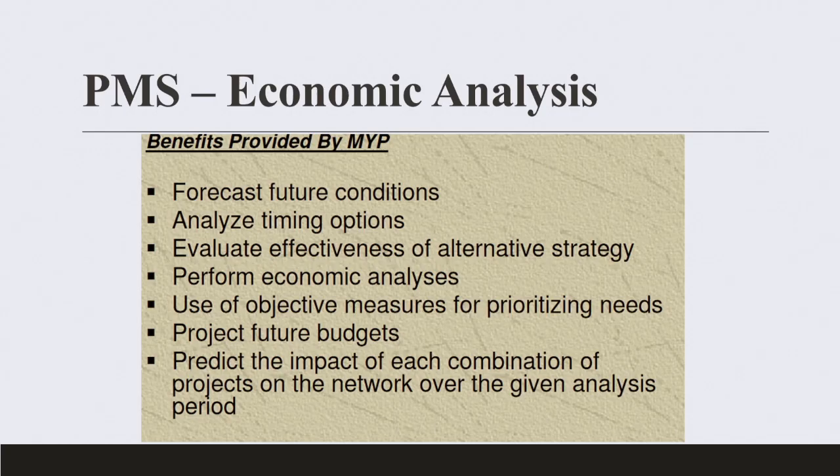Should I do maintenance? If I do preservation, is it fog seal, slurry seal, chip seal, mill and fill, ultra thin bonded layer, FDR? All these are different types of preservation activities. Each one has a different magnitude, extends for a different lifespan, but costs you much. You know, you get what you pay for.